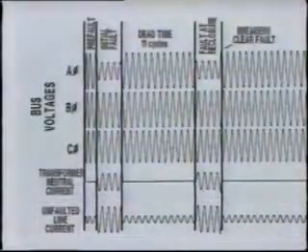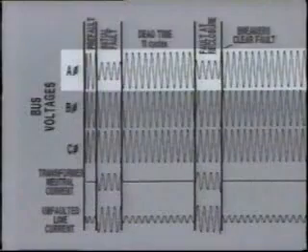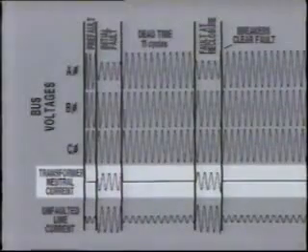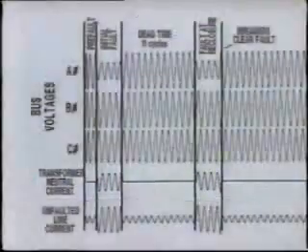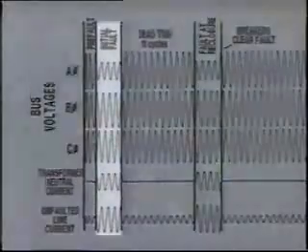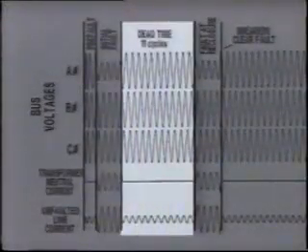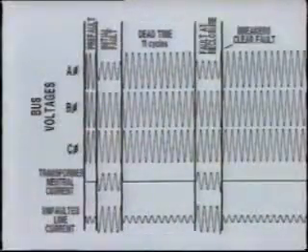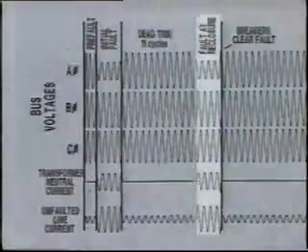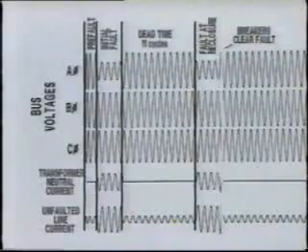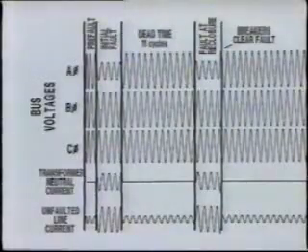From the bus voltages, we conclude that the fault is a single line-to-ground fault on A phase. This is confirmed by the transformer neutral current. We can also tell that the fault duration is 4 cycles, and the line dead time is 11 cycles. At this point, the breakers on the faulted line reclosed, but the fault was still there. So the breakers immediately tripped out again and locked out.